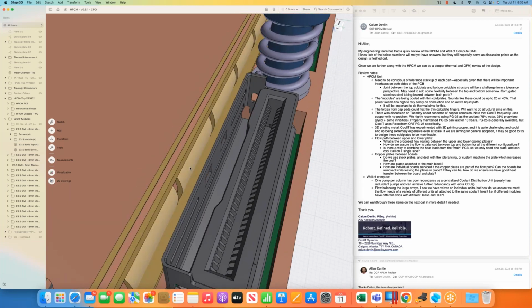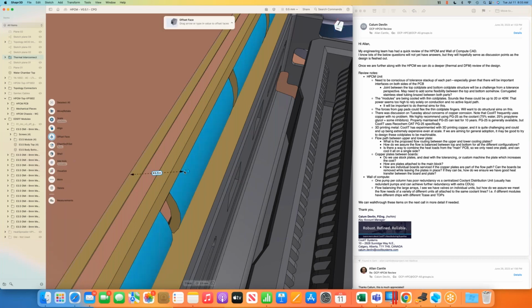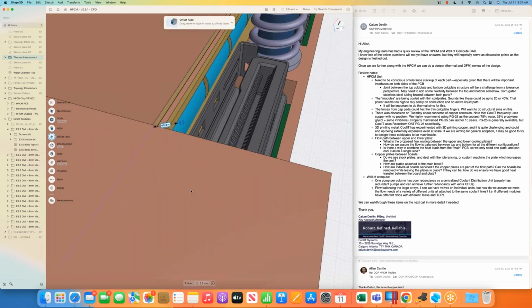So I mean, these are spring-loaded pins, so they're like a gap pad, but there's an air gap underneath them. So I was thinking whether we can actually design these plates, and when we attach these plates, they might be somehow physically mounted to the actual cold plate, and behind here, I was thinking that we could have some gap pad material. So as the module gets inserted, it compresses these and pushes up against the gap pad. So that's what I'm hoping we can get properly simulated.